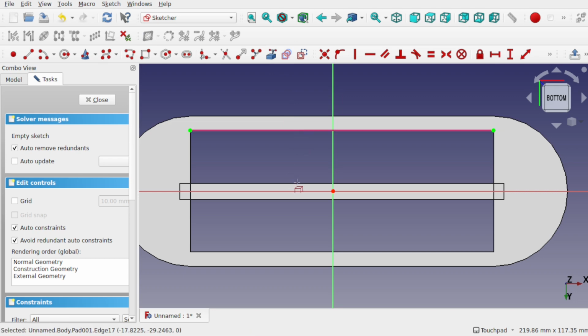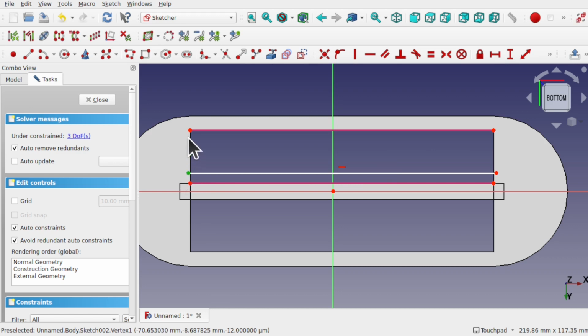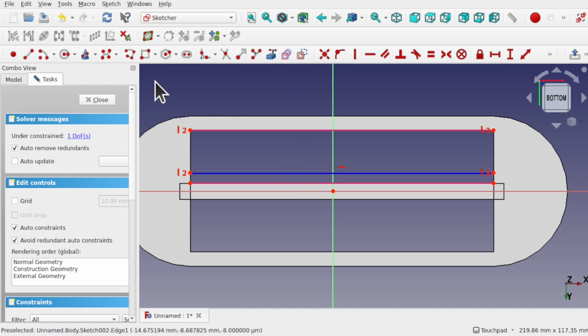And we're going to create a zigzag pattern in here for the framing. I'm going to start with another line because we're going to have to create framing that's basically walled. So it's got two sets of zigzag lines, so we can create some closed geometry, and this is going to be construction geometry. And we're going to use the polyline tool, take from this point and connect up.